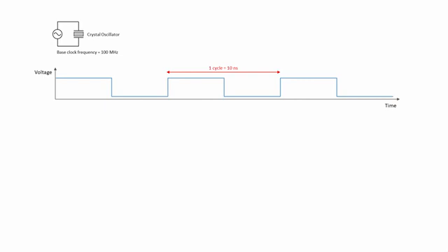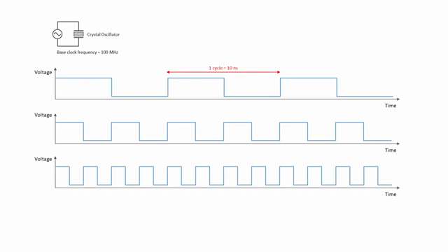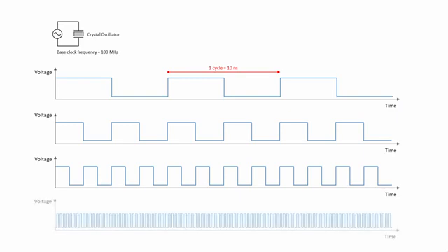This is called the base clock frequency because the oscillator sets the tempo for many of the computer's components, including the CPU. Special circuits inside the CPU, called frequency dividers and frequency multipliers, take this reference signal and multiply it up to a much higher frequency that can be used to control the rate at which instructions are executed. For example, multiplying a 100 MHz base clock signal by 35 will give a frequency of 3500 MHz. That's 3.5 GHz, which is a typical CPU clock frequency. The time for one cycle at this rate is less than a third of a nanosecond.